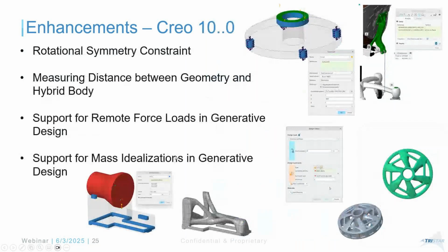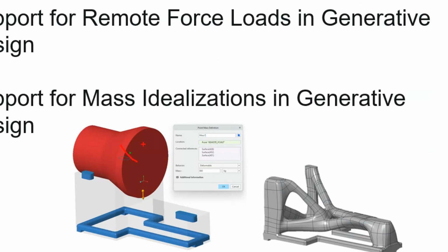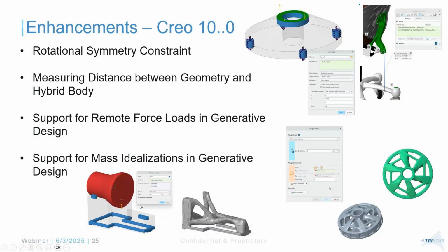That's awesome, right? Instead of giving a planar symmetry, you're also able to give rotational symmetry and do idealizations like in regular FEA, where I have an object here where I do know the CG location. I don't really care about that. Can I apply a load there as a mass element, apply an acceleration of 1g to it, and then distribute that load? We do that in simulation quite a lot, but it's nice that more and more things are being added to this with each release.